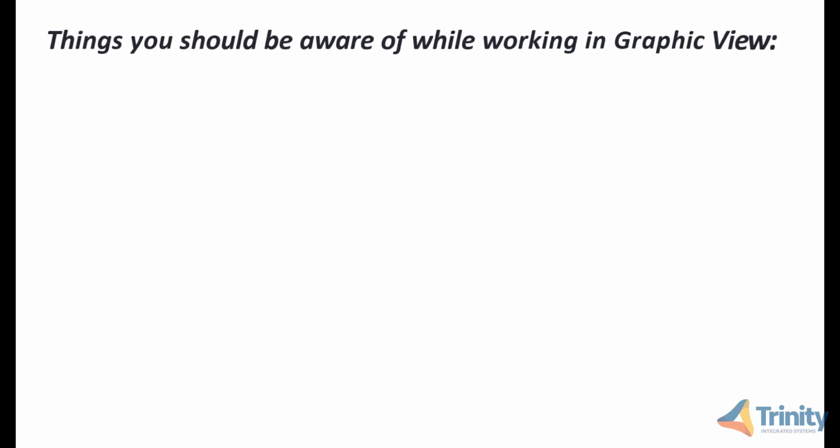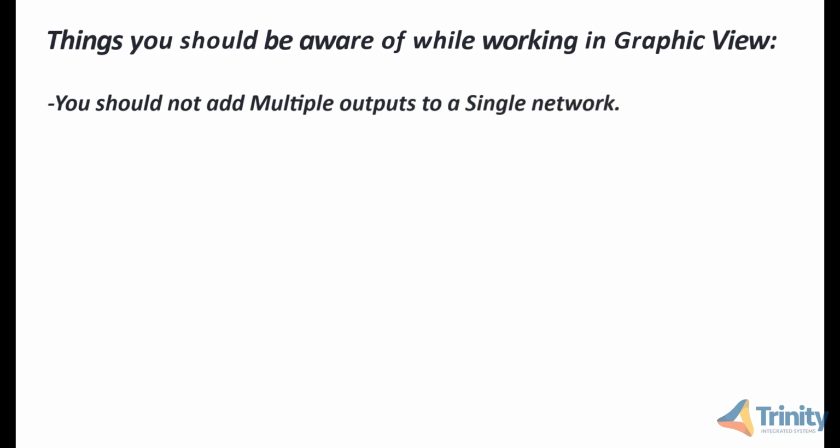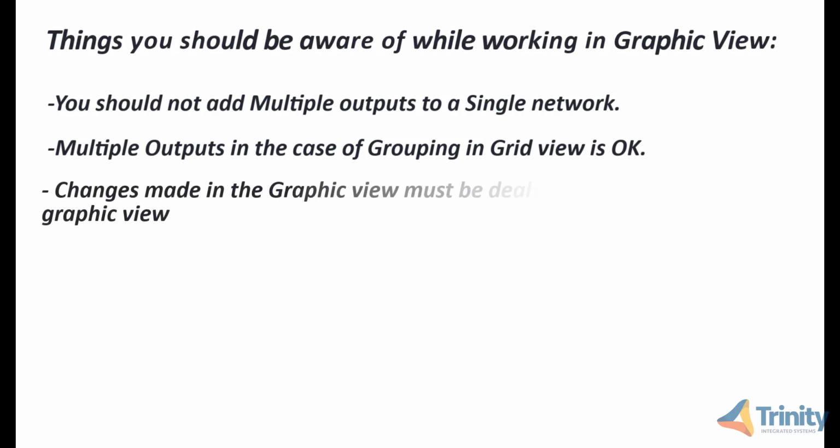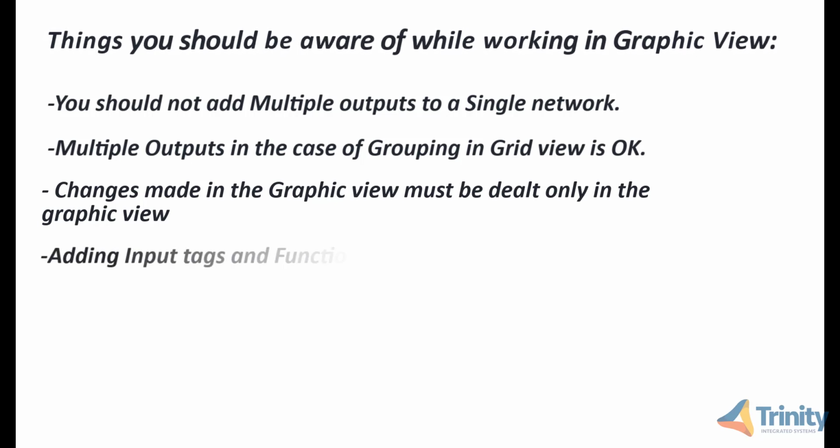Things you should be aware of while working in graphic view. You should not add multiple outputs to a single network. Multiple outputs in case of grouping in grid view is okay. Changes made in the graphic view must be dealt only in graphic view. Adding input tags and function blocks are permissible.